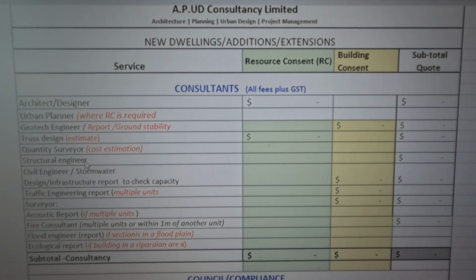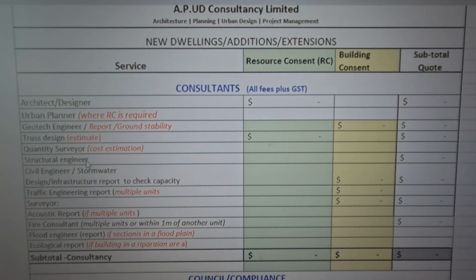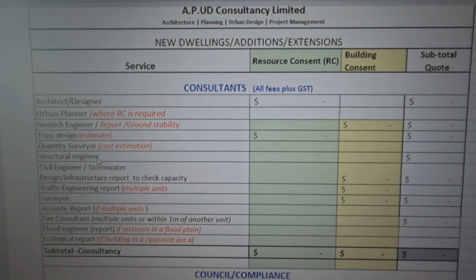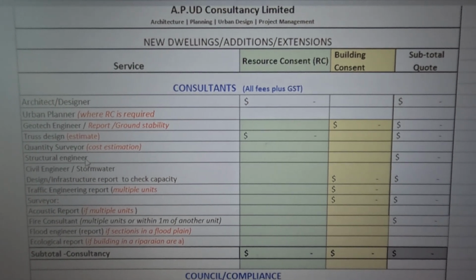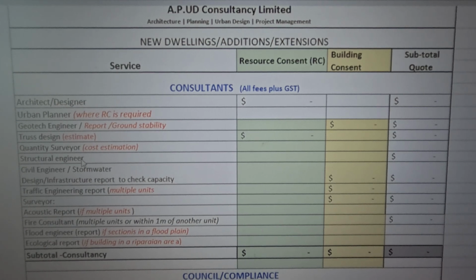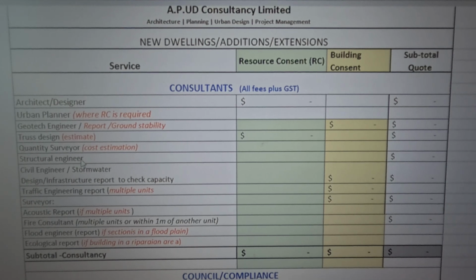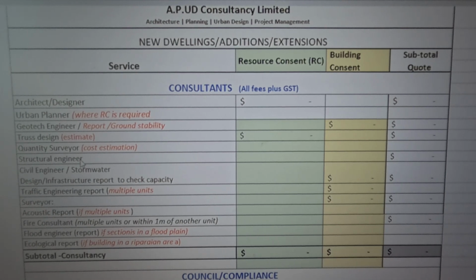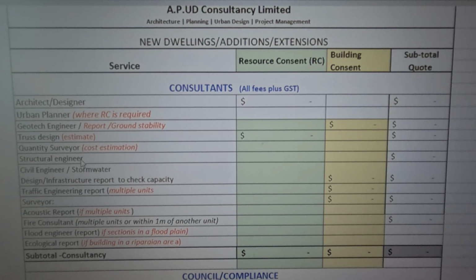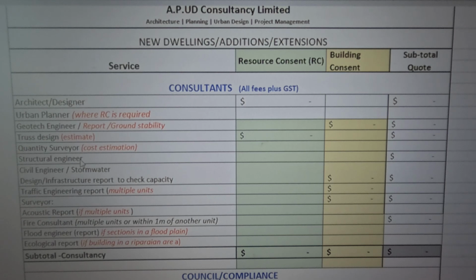Quantity surveyor: you may or may not need a quantity surveyor. This is a call you have to make as a developer or as a client, because a quantity surveyor will give you the cost estimate of your project. Sometimes I've seen clients just take the complete, detailed drawings and give them to a builder to cost directly. But some builders don't have the necessary skills to cost the project, so the builder will then take those drawings and give them to a quantity surveyor to do the costing.